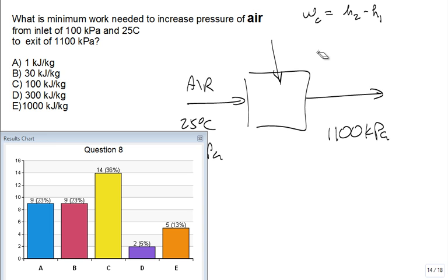Yes? Do you agree? I like constant specific heats. It's air. It's an ideal gas. I really want you to bone up on constant specific heats. Why? Because you can do back-of-the-envelope calculations so quickly, right? So is this Cp (T2 minus T1)? Yes. All right. This is the hard part. What is roughly the specific heat of air, Cp?